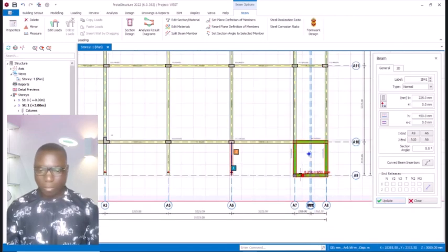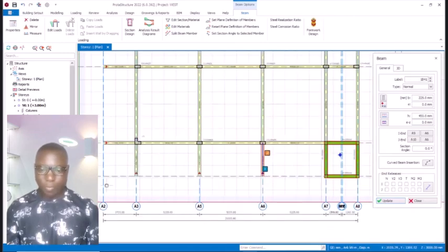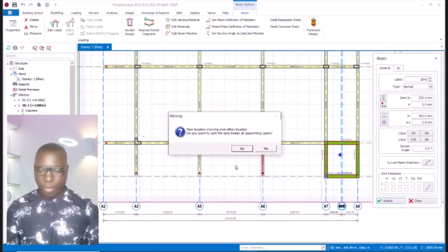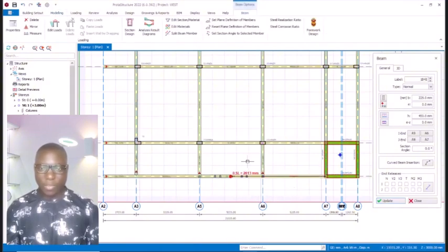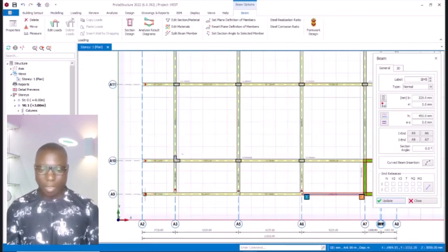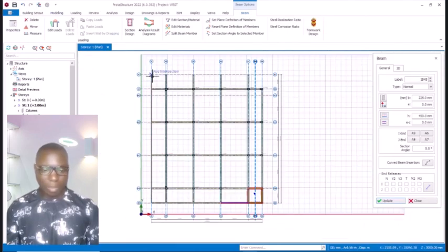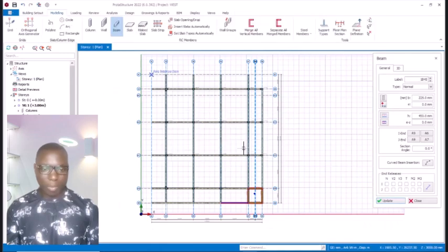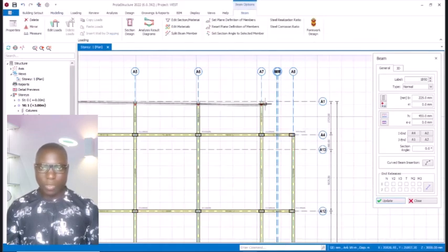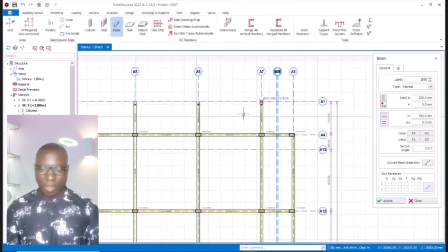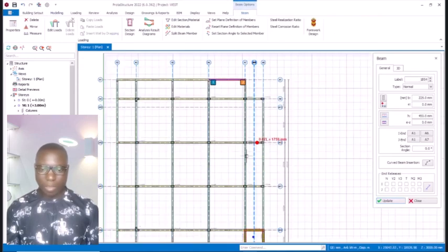Okay, so at this point I want to pick from this point to connect this beam up to the shear wall. I'm going to split it. Alright, so I'll click on the use options to split it, just like this. Same thing applicable here. I'm going to split it right here. Yes option, and then I connect it to this point. Yes options, just like this.